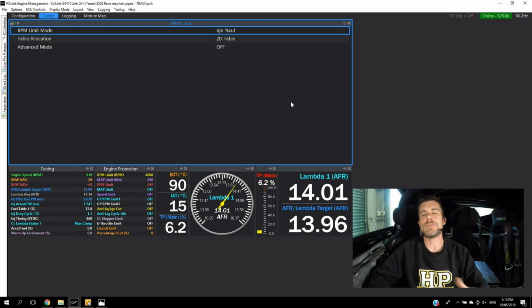An aspect that is often overlooked or misunderstood is the fact that in a port injected engine, some amount of the fuel delivered by the fuel injectors will end up wetting out the port wall. It forms what is referred to as a fuel film. So when we actually cut off the injector, there is still some amount of fuel making up this fuel film on the port wall, which will still be drawn into the cylinder.